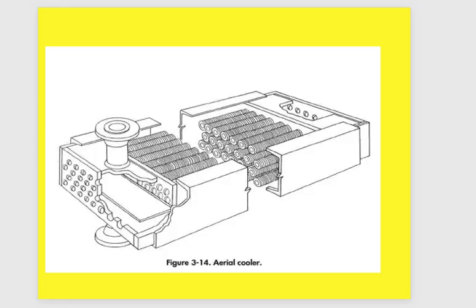In many cases in the refinery or gas plant, you cannot put water directly to cool down or condense the stream because it may boil up or something like that. So you have to use the air cooler first to adjust the temperature, then you will use the water cooler. And there are many applications for the air cooled heat exchanger.